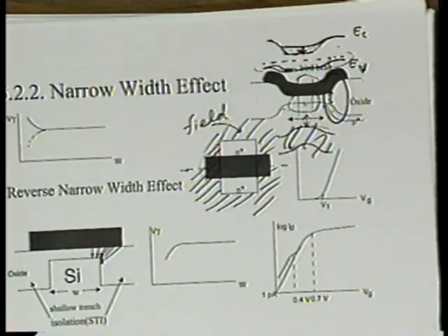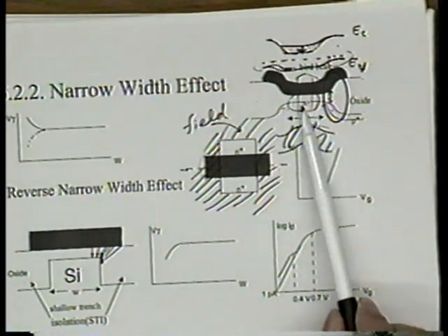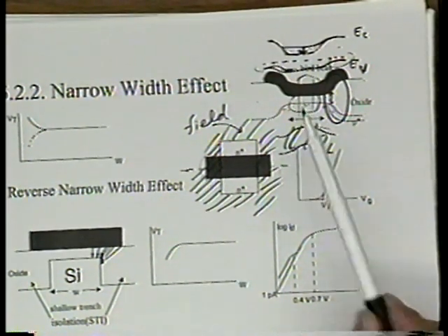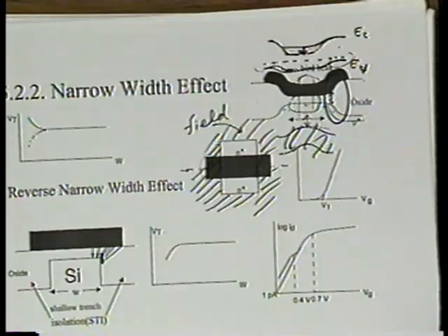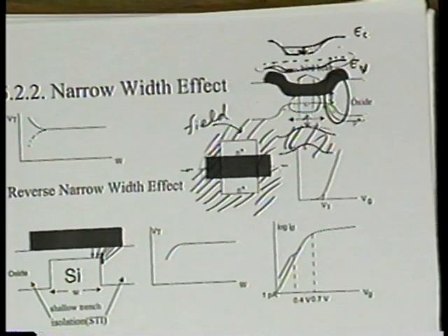Is that right? Okay. So now you would know, you would not ask, gee, even though I have a high threshold voltage region here, the VT should not increase, where VT is measured at the first VG at which current starts to flow. That would not increase, but the fact is it will. Can you see that? All right. Okay. So VT will increase as the W decreases.